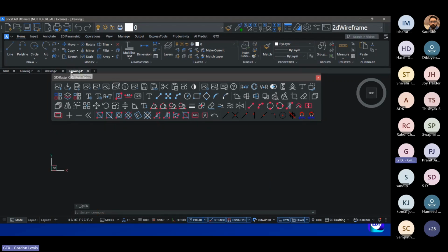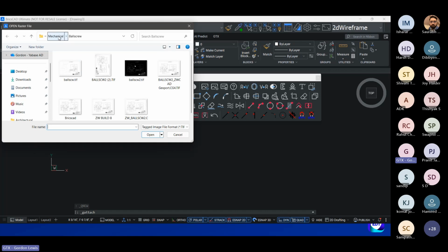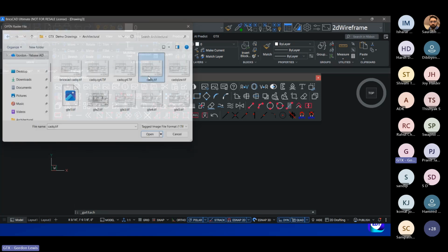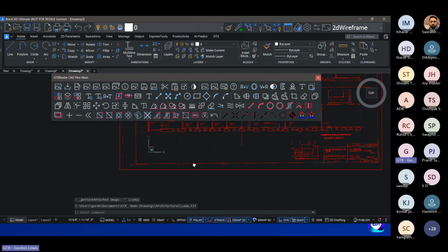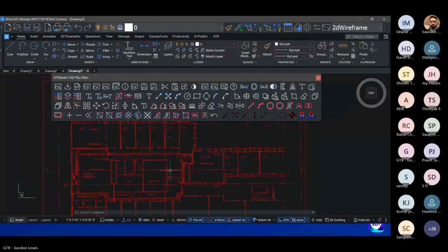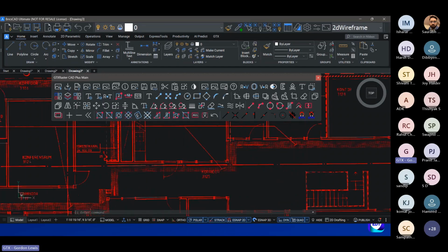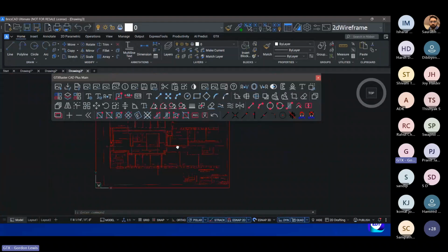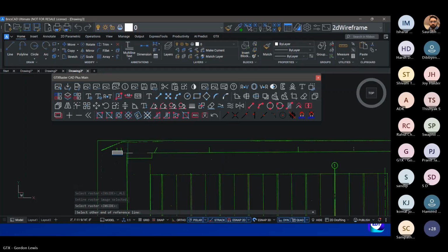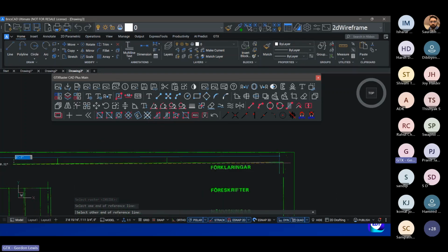So moving on, I'm going to open up another drawing just to give you an idea that it doesn't matter the type of drawing that we work with. So this is a building layout. It's a TIFF file. Can't do anything with it, but I might want to make some changes to the drawing. So if I zoom in, actually, I'm going to do a deskew on it first, just to make sure it's square. I'll do a deskew on the drawing.